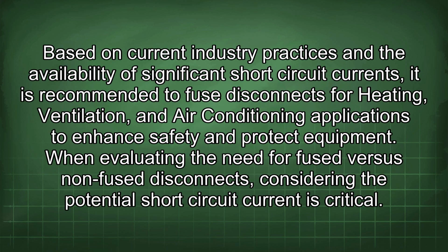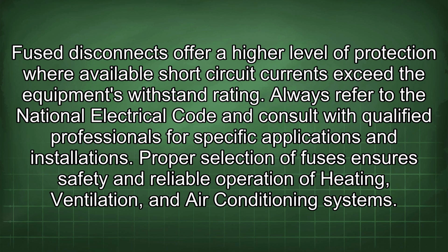Based on current industry practices and the availability of significant short circuit currents, it is recommended to fuse disconnects for heating, ventilation, and air conditioning applications to enhance safety and protect equipment. When evaluating the need for fuse versus non-fuse disconnects, considering the potential short circuit current is critical. Fuse disconnects offer a higher level of protection where available short circuit currents exceed the equipment's withstand rating. Always refer to the National Electrical Code and consult with qualified professionals for specific applications and installations.